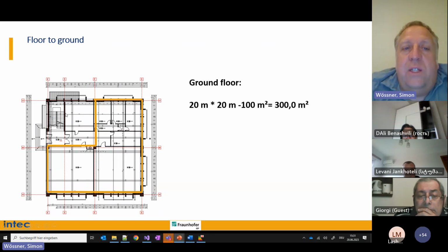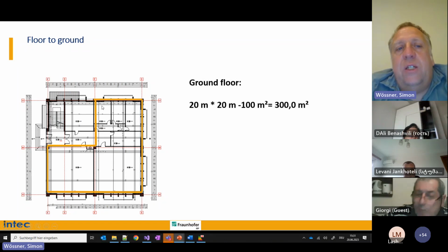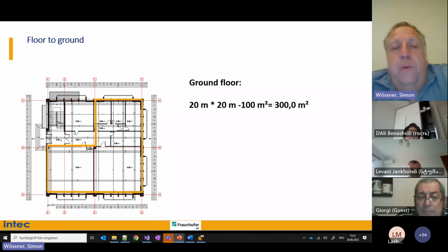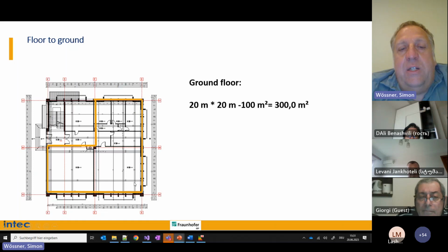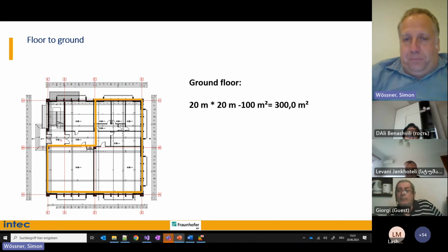So we don't consider that, and that is not anymore a floor slab, but the ceiling of the basement or the floor of the ground floor. So we do not have to consider that for the declaration of conformity and also the minimum energy performance requirements. That is only that part of the ground floor which actually is heat transferring.